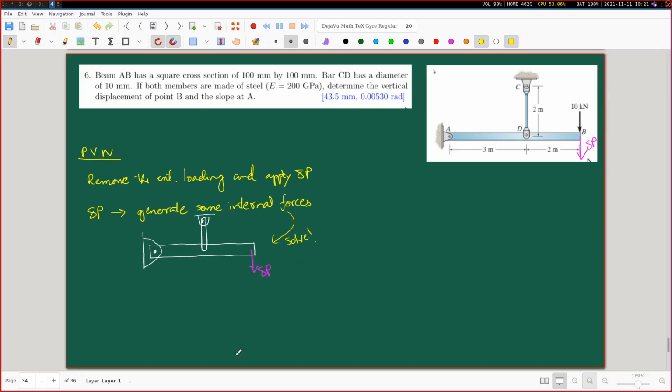Now, once you solve for the internal forces, if we quickly write down here that general expression, we have delta P into delta is equal to sigma delta F into U. So this delta P is known. In response to that, we have just determined the delta F, rather we have determined the delta F's wherever we wish to find them in this problem. Now what do we do? Now you bring back the external loading.